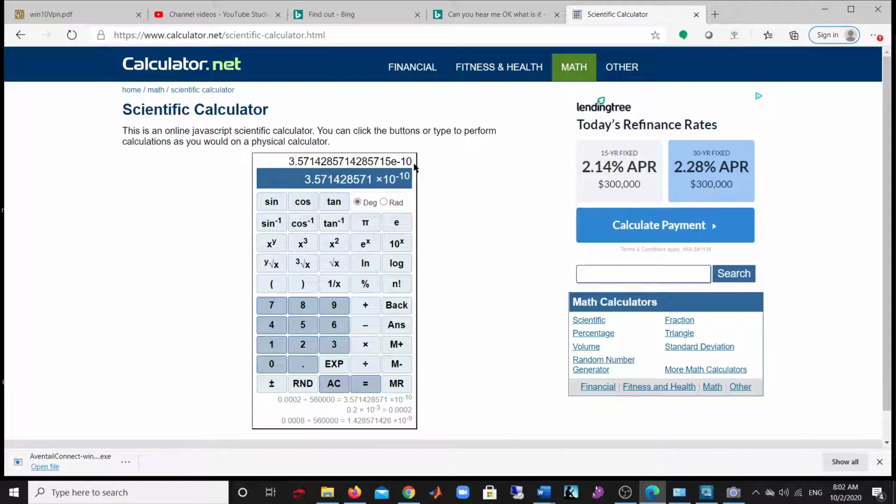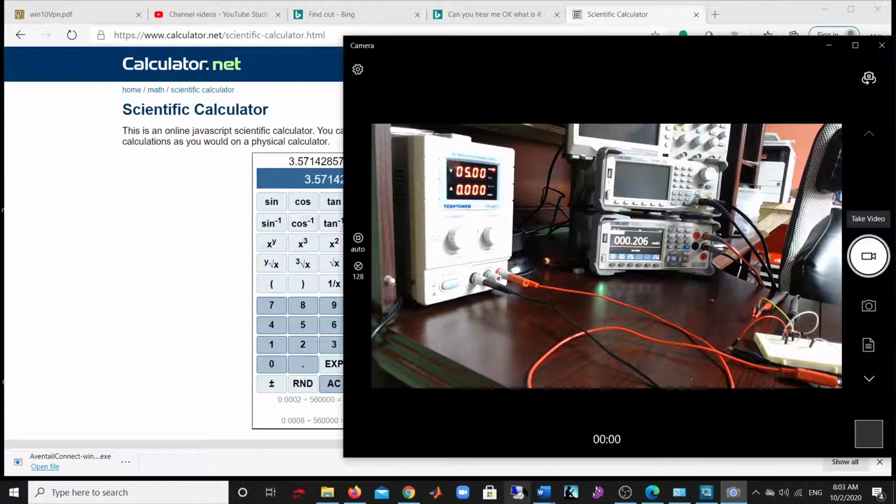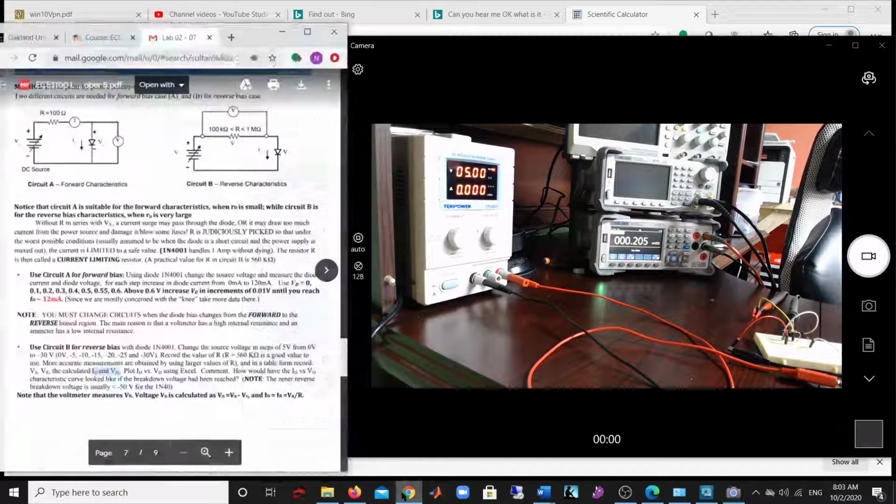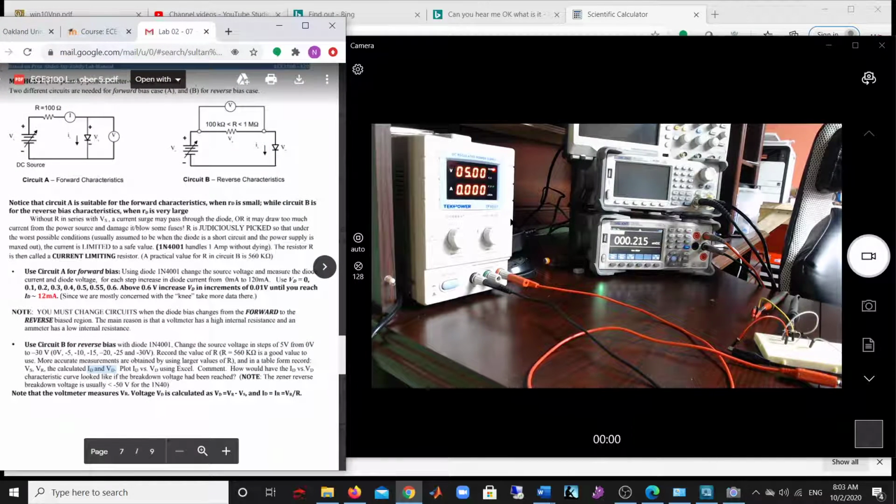And if I have the current there, obviously that's the same current as the resistor. Plus the VD, everybody knows how to get the VD, because we talked about this many times. Kirchhoff's voltage law, right? So this voltage minus this voltage will give the VD. You can calculate it. And ID, I showed you how we calculate it.